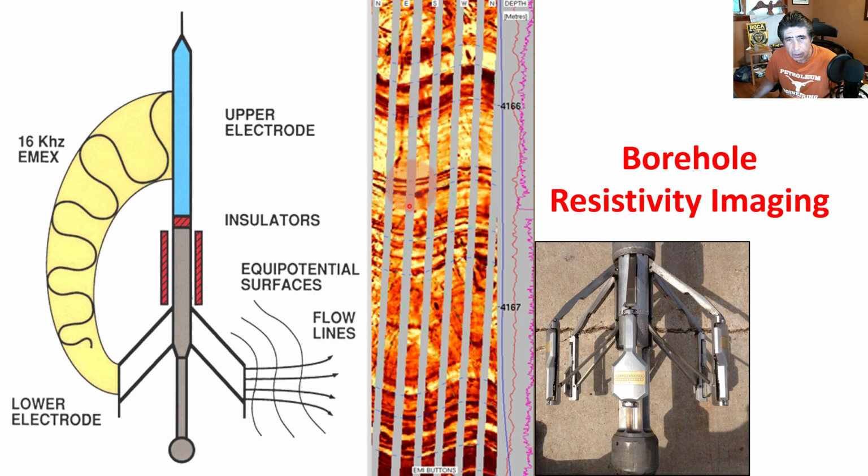The gaps in dark and light color are an indication that there was no coverage of the borehole right there. The reason is that these pads do not cover the 360 degrees of the borehole surface. They only cover a section. And the reason why these gaps are not straight, and are moving, is because the tool is rotating as it acquires measurements. All of the tools used to acquire images have to run very, very slowly compared to the logging speed of conventional logs.